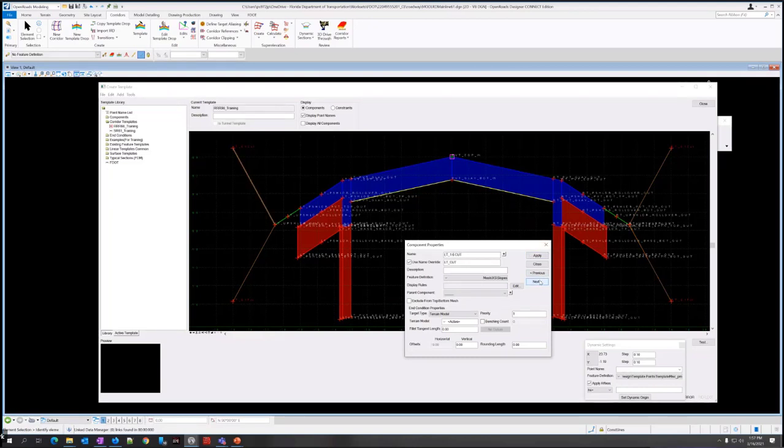I think we're probably going to make the same change on the other one here. So I'm going to click next and let's see if I can get to the left fill. If you click next twice, it looks like it's bringing up the left 1 to 6 fill, and it does make it kind of bold in this window. So that may help you figure out which one is selected. But you can also see the name is LT 1 to 6 fill, and that one also needs a priority 2 as well. So these can be the same as the other side. It's just kind of a branch. So coming from this, it's building the template, it comes to this point and says, okay, I got 2 end conditions. Let me do the first priority. And if I can't do that, I'm going to do the second priority.